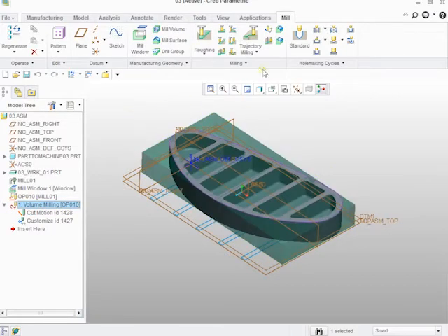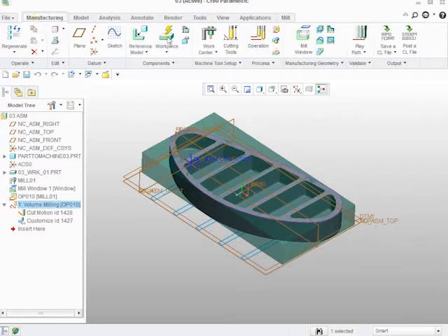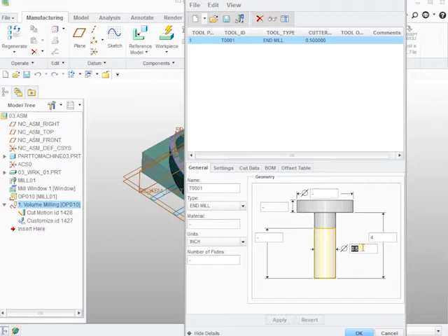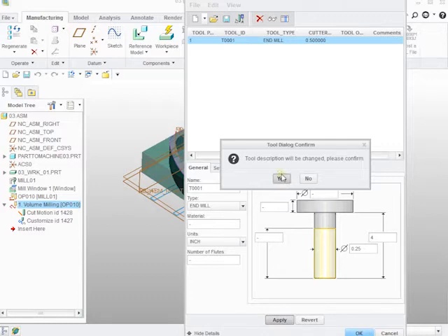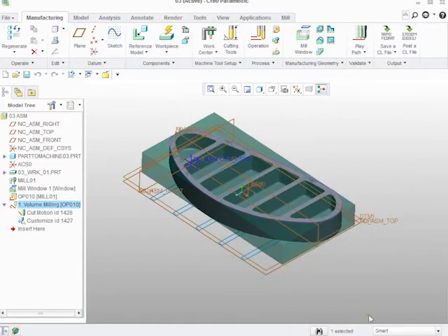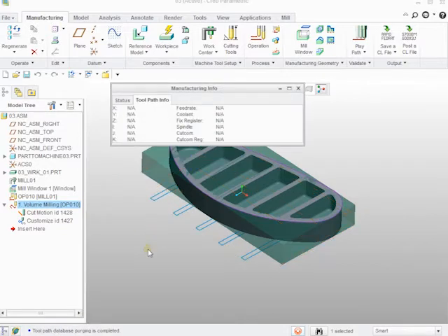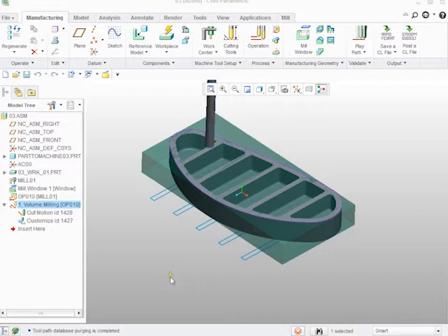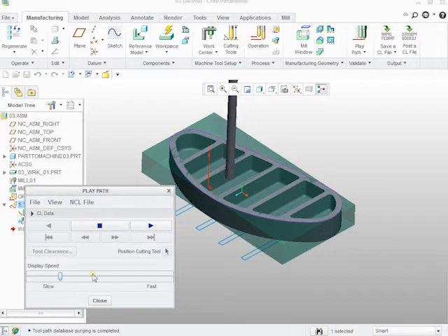Let's go ahead and change some items. Let's change our cutting tool. I'm going to change that to 0.25. Confirm. Okay. Now let's left click, right hold down, play my toolpath here, and as it does this recalculation again at the bottom, you'll see that it brings up a smaller tool. Okay, so a smaller tool, and I can certainly speed that up and slow it down.